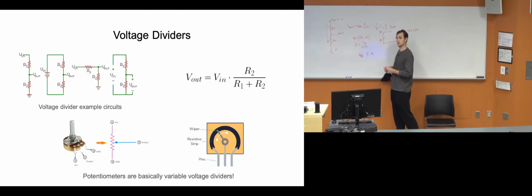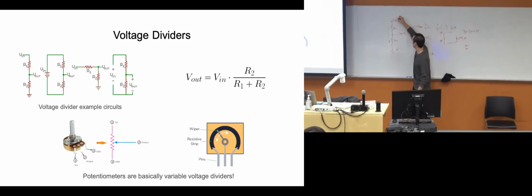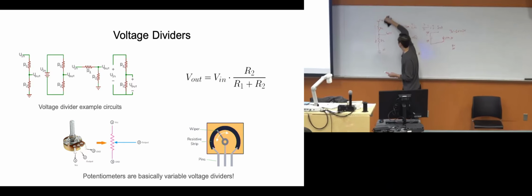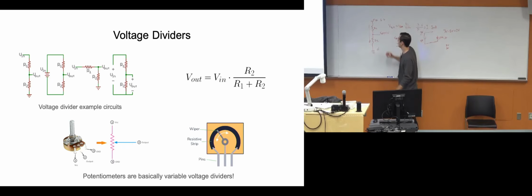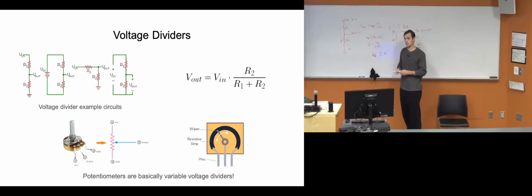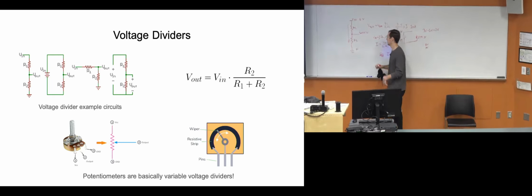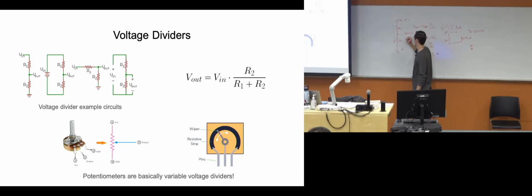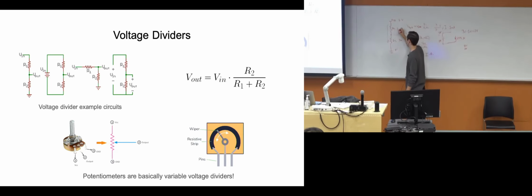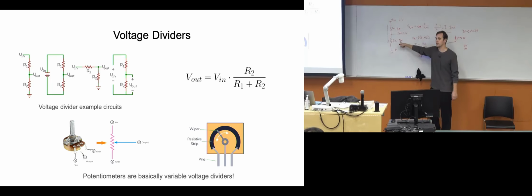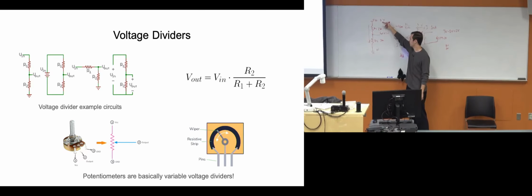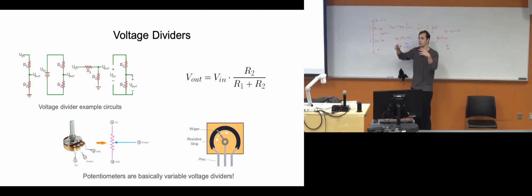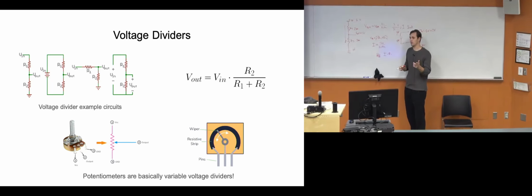So we have 5 and we want 3. Yeah. Let's say in this example, I'll erase it. We have 5 volts up here, and we want 3 volts right there. So I guess we could have the bottom one be like 3 is like 3:2, so it would become 3/5 and 2/5. Right? So then if we translate that to thousands, we can put a 2K resistor here, 3K resistor here. It's 5K total. And we have 5 volts. So we know it'll drop 1 volt per 1,000, right? And we have 2,000, so it'll drop it down to 3. Does that make sense how she did that?